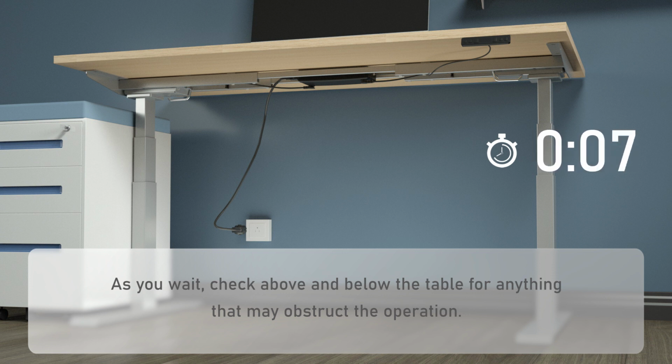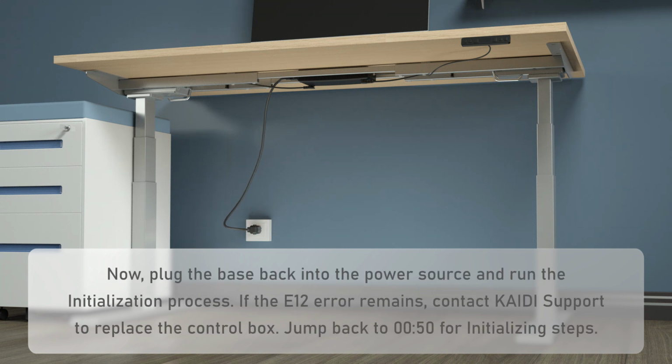As you wait, check above and below the table for anything that may obstruct the operation. Now, plug the base back into the power source and run the initialization process. If the E12 error remains, contact Kaidi support to replace the control box. Jump back to 050 for initializing steps.